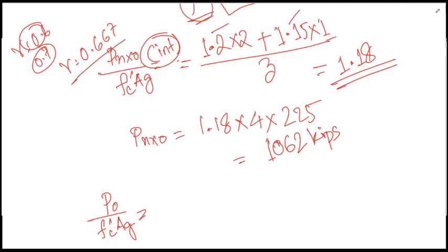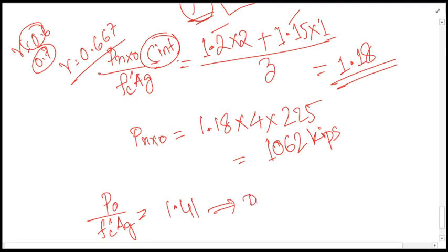Again we'll be getting the same value, whether it is 0.7 or 0.6, it doesn't matter. e by h will be 0 in this case, and for 0.4 you'll be getting 1.41 in both cases, gamma equals 0.6 or gamma equals 0.7. So we get 1.41, and from there P naught will automatically be the same value as we obtained in the last calculation, that is 1269.